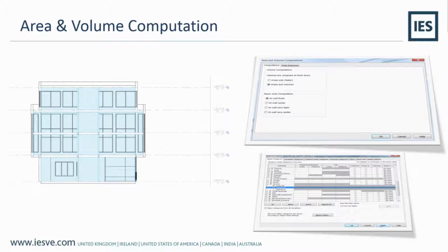One of the other key things to set is, if in plan view you've placed a room or a space throughout your model, you need to check how they are actually being applied vertically up through the building and, more importantly, how you're handling the ceiling voids. Are you considering them within your model? Are you going to set these spaces or volumes so that they go from one finished floor level to the next, and you'll deal with the ceiling voids in another method? Again, we'll go through these options today.